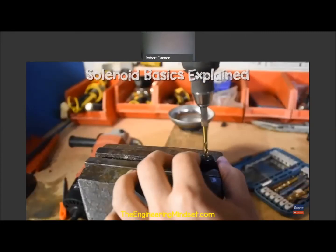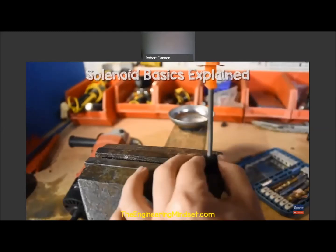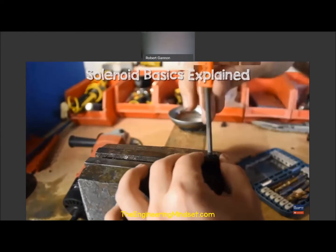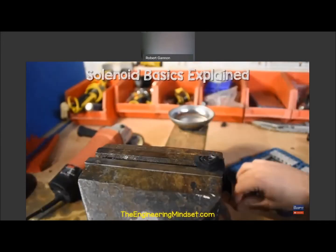Now that I've melted and shaped the ends, I just need to drill through the excess in the center to allow the piston to oscillate. I'll also just file it down so it's nice and smooth and the piston doesn't catch on the edges. For the piston, I'm just going to use the iron nail. Now we need to wrap the coil.